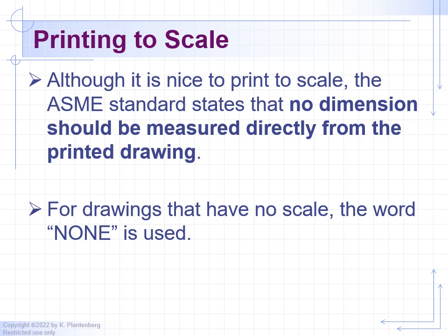That is a massive no-no, in part because drawings are always going to be printed with some aspect of scale in most cases, and that's not the way we go about it. In terms of measuring the object, you take that from the dimensions, right? The dimensions are the ones that are actually printed on the drawing itself, and that's how you get all your dimensions to create your object. Never actually measure from a drawing.